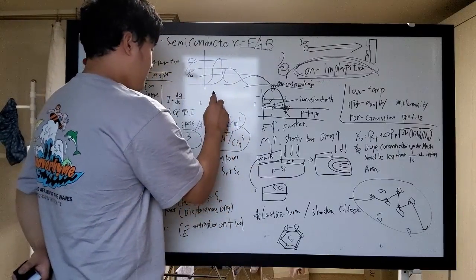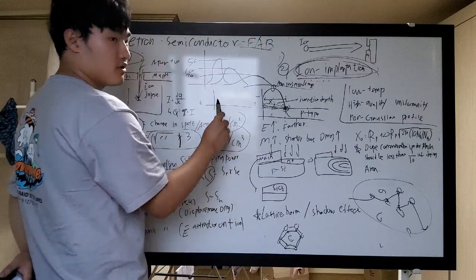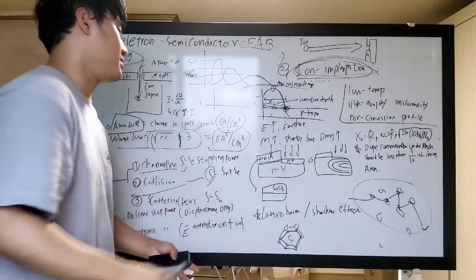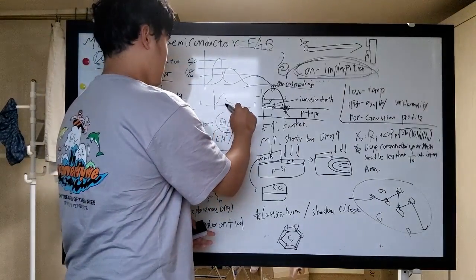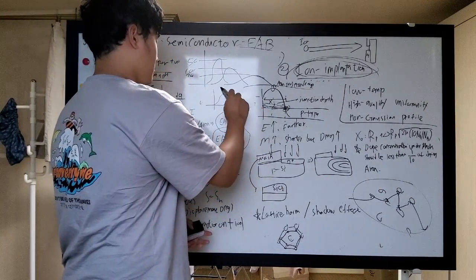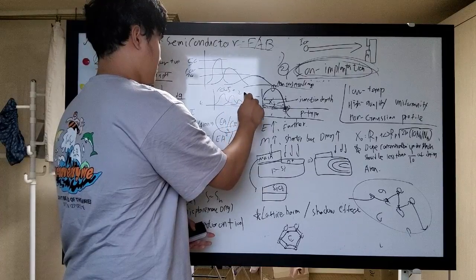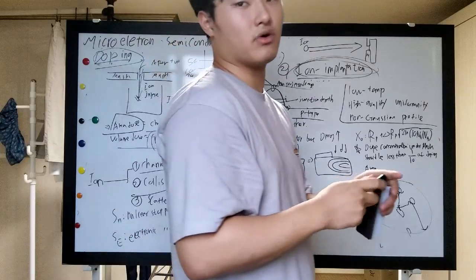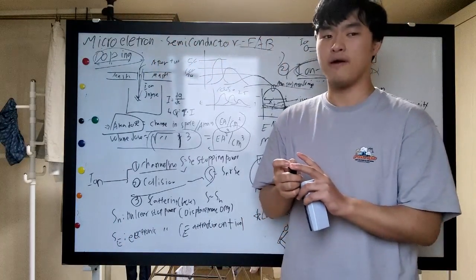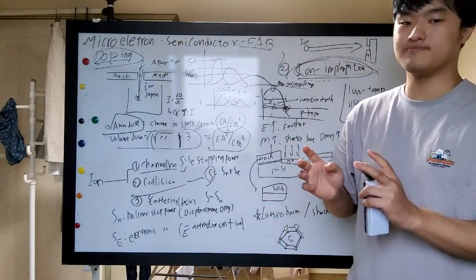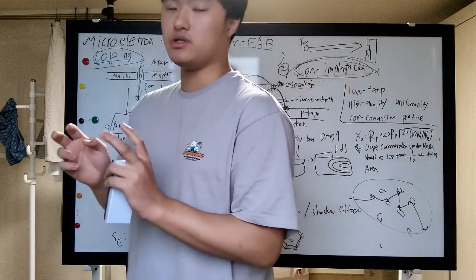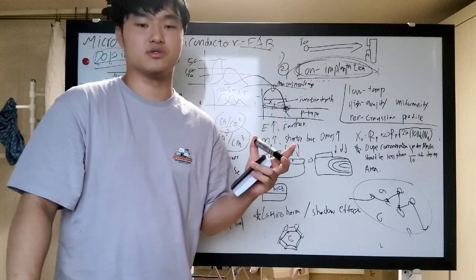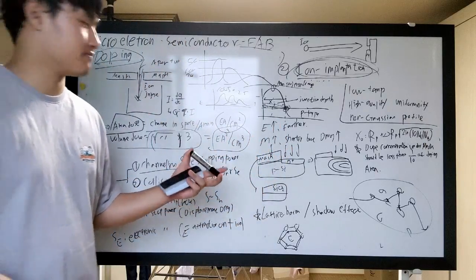And for the mass, with the same energy, if the mass is heavier, then the dopant will go less distance. If it is lighter, the dopant will go deeper inside. But the heavier the dopant is, the more damage is induced during the collision or impact. We will talk about this later.